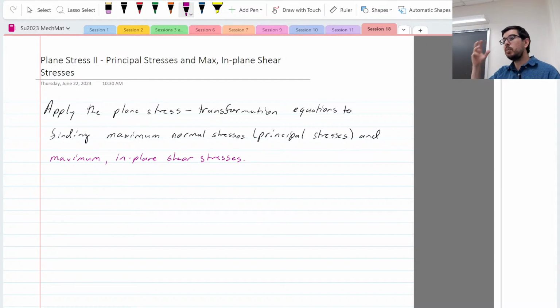Okay, and so being able to even see the stress and strain distributions on your CAD in the computer and be like, oh yeah, that's an equivalent stress. And I remember something that we talked about in mechanics of materials to relate that to what kind of shear stresses might be occurring. And if I change the geometry a little bit, I can reduce the shear stress, or I can change the geometry a little bit and reduce the normal stress, whatever it might be.